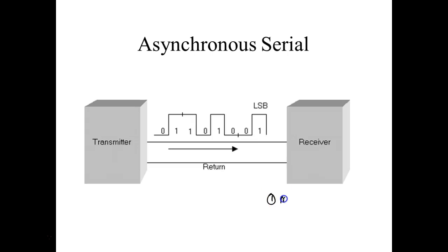What we have to have is, number one, we got to have a magnetic field. And 2, we've got to have a conductor. And 3 is we got to have what we refer to as relative motion, which means we got to either cut the conductor through the magnetic field, or we got to move the magnet across the conductor. And this is going to induce a voltage into that conductor.